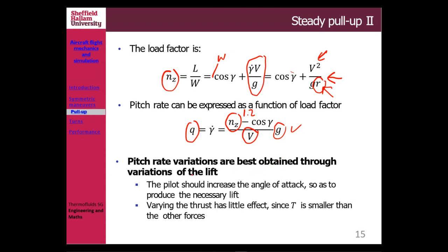Okay. Now, obviously, pitch rate variations. This is the one that your pilot should control, rather than pull abruptly on the joystick, for example. That makes your pitch rate quite high. If your pitch rate is quite high, then your load factor or G force is quite high as well.